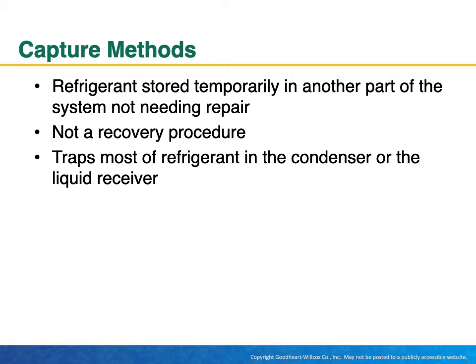And then from the condenser onto your evaporator, that whole line set, your evaporator will have no refrigerant. You could do repairs and then just pull a vacuum on that section. And once you're done, open up the valves and all your refrigerant will flow back into the system.